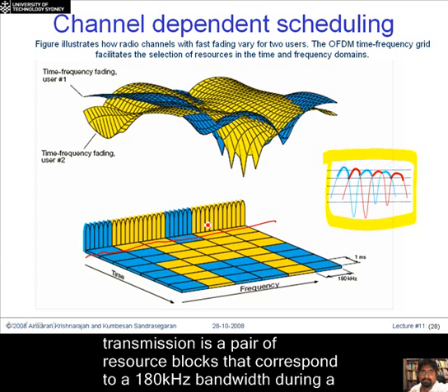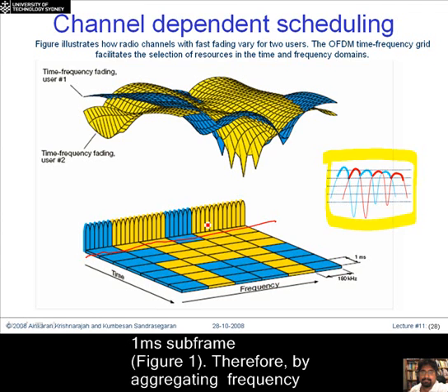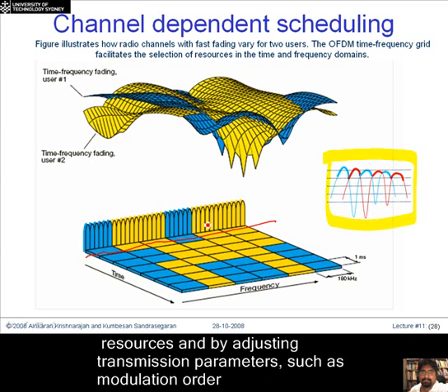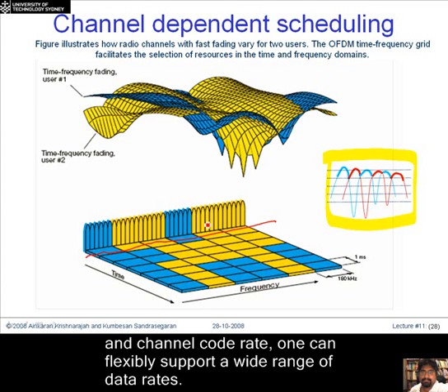Because primarily you are looking at the different frequency bands that you have available and allocating the best to the best user, allocating each resource block to the user that has the best measurement, or the best channel quality, on that particular resource block.